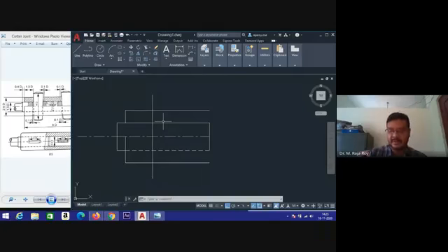Okay. So slope 1 by 30 equal to h2 minus h1 by L. That is the formula. So h2 value we have to calculate now. This is 2 times h2 minus 39 equal to 2. You will get h2 value is 39 plus 2. That is 41. Okay, this is the calculation I will show to you.